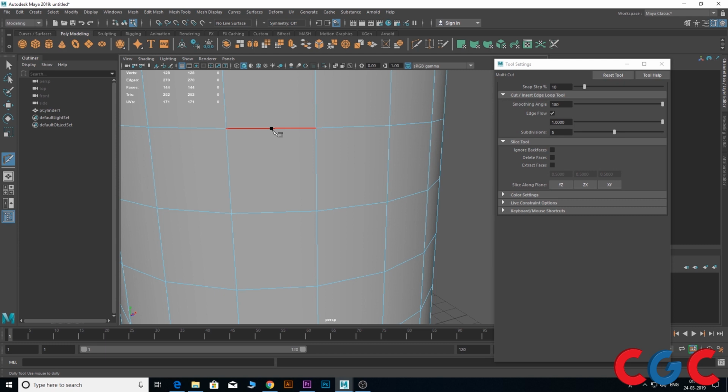When I press left mouse button now, I can see a number 50. 50 means 50% from this point. Now it will show 10% from 20, 30, 40. This is the increment because of this number 10. If I press 25, before pressing 25, I have to remove this dot. How do I remove?